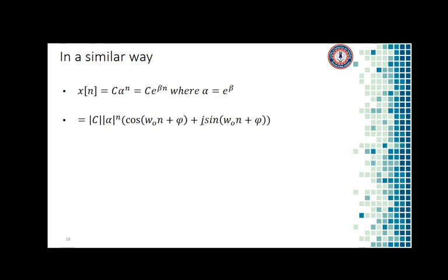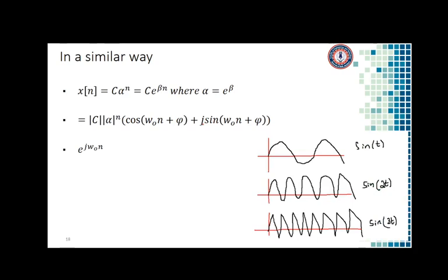The last thing I am going to talk about is periodicity in discrete time signals. I talked about how in continuous time, sines and cosines can keep on increasing in frequency. If I look at this picture, there is nothing to prevent me from continuing to oscillate faster and faster. So I can talk about a cosine of 4000 hertz or 40,000 hertz, getting faster and faster, but that is not true in discrete time. Discrete time sinusoids look different. So let's take a look at a discrete time sinusoid.